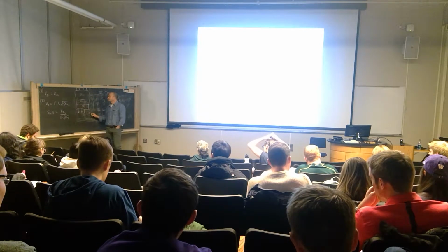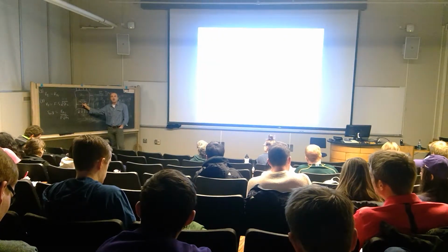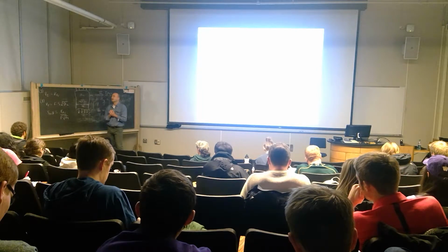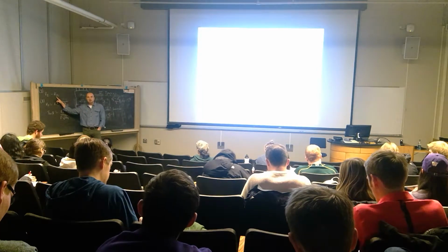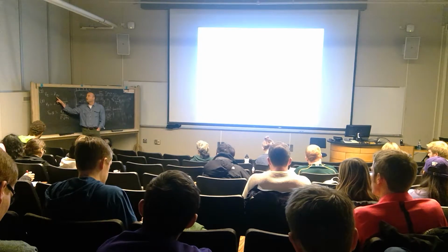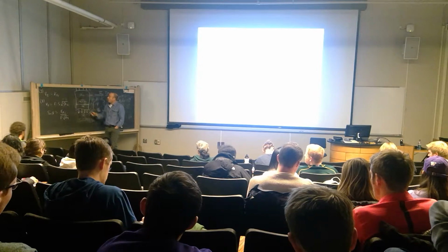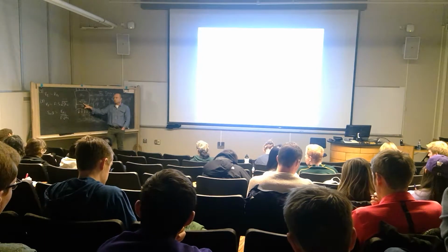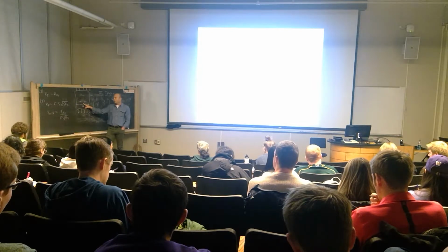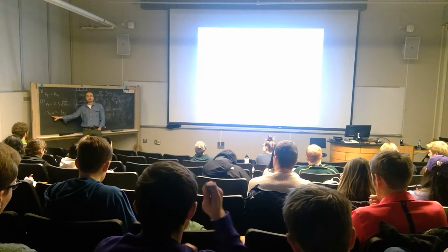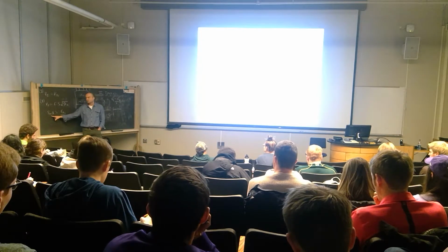When we look at this, what we can do is assess what we think to be the critical stress that's present in our structure for a specific crack length. And so the way that this is often used for design is to say, if I know what the fracture toughness of my material is, I chose my material for my design according to partially that property, then what I can do is say, well, how long can the crack be before failure will actually take place? And then I look to see, is the critical stress less or greater than the stress I expect in my structure?